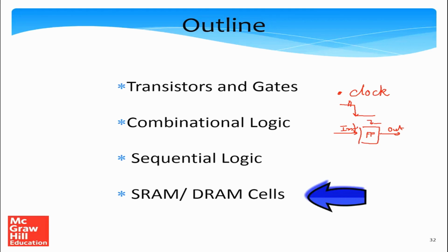So this is essentially a storage structure where the inputs get reflected at the output at the time of a negative edge, and in general the value is saved in the structure till the next negative edge. With this we can create a lot of sequential logic: counters, frequency dividers, a host of digital circuits.